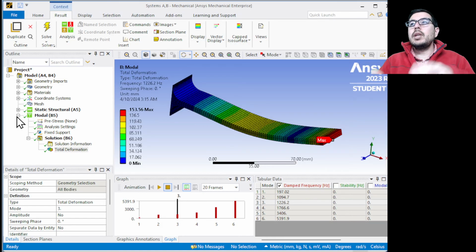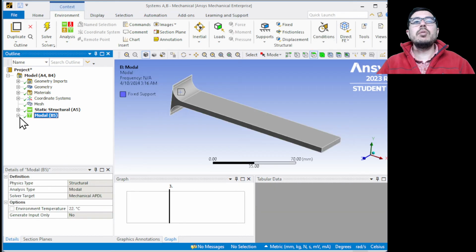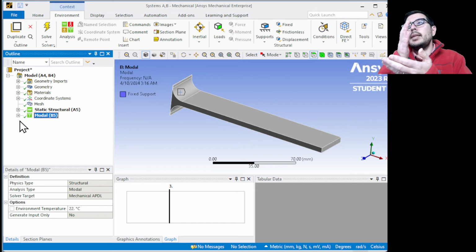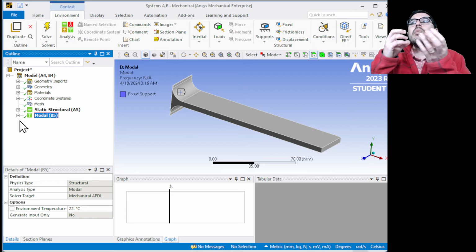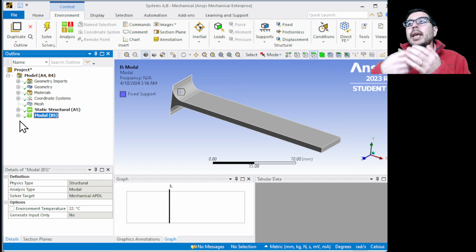If you want to see how to do that using a power spectrum in Ansys, check out the tutorial from the Ansys Learning Forum. But for us right now, I'm just going to show how we can interrogate at a particular frequency. So if we were to hit this system with a particular frequency, what is the type of response? What is the amplitude of the stress that we would expect?